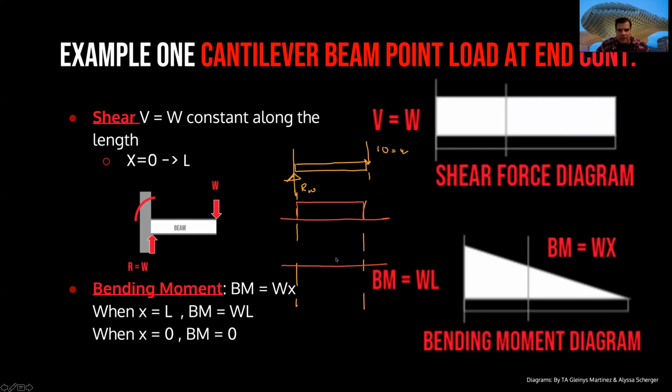And for the other diagram, that is the moment diagram, I start at 0, I finish at 0, and what I will do is tell myself, if I cut the beam just before R2, I have 0. If I cut at 1 unit, if I cut at 2 units, if I cut at 3 units, what is happening?